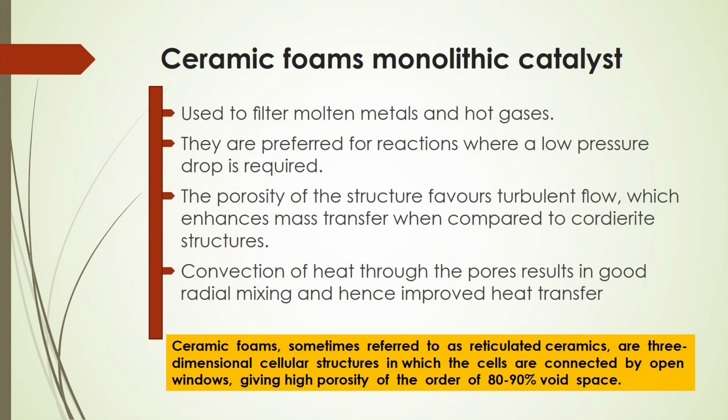That is why ceramic foam is also used as an alternative to the ceramic monolithic catalyst, because it has the advantage of a low pressure drop in the reactions where the pressure drop needs to be low. Also, the porosity of the structure may favor turbulent flow, enhancing mass transfer, and in this case it has advantages over the cordierite structure.